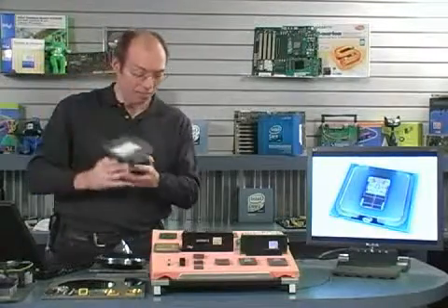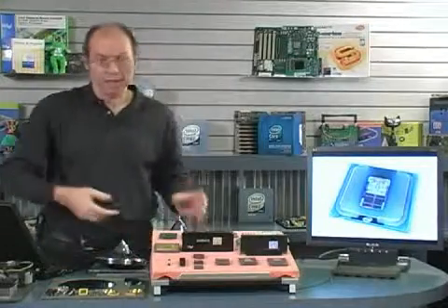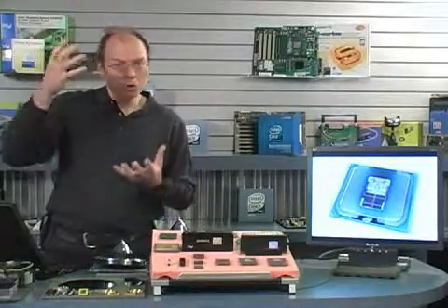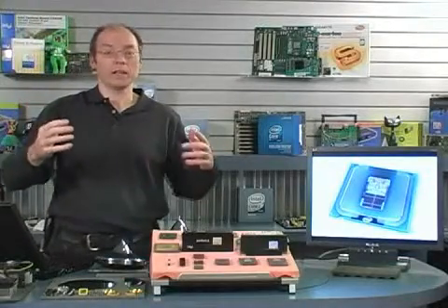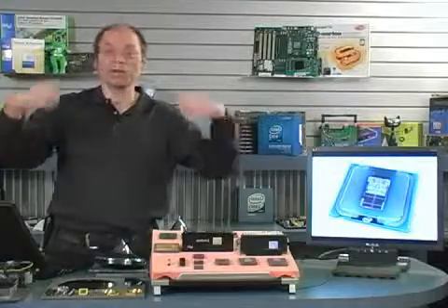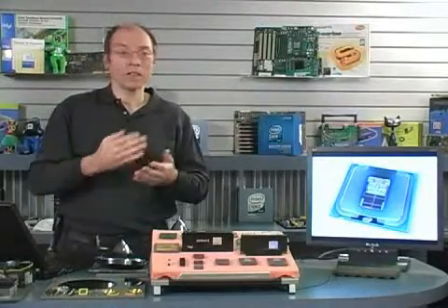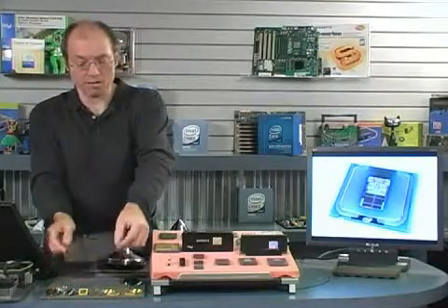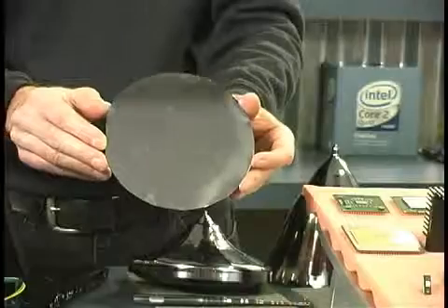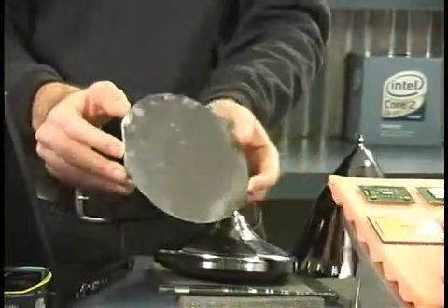The head and the tail are then chopped off of this crystal. So now what we have is this cylindrical crystal of silicon, head and tail cut off. It's ground so that it's perfectly round, and then it is put into a saw that cuts it into thousands of plates called wafers. I have an example here of a wafer that was cut from one of these crystals. You can see that it's round and is very thin.